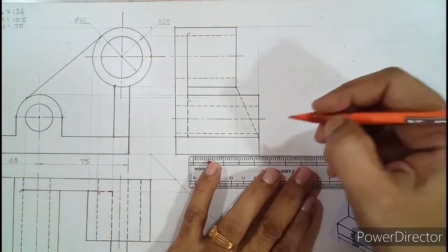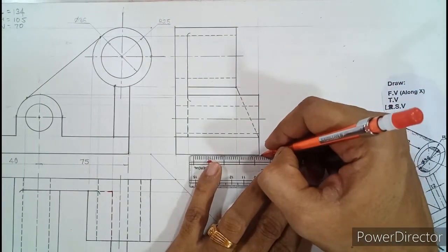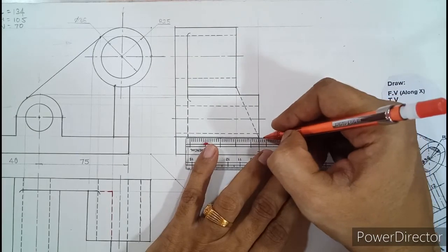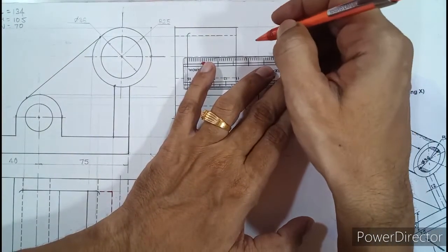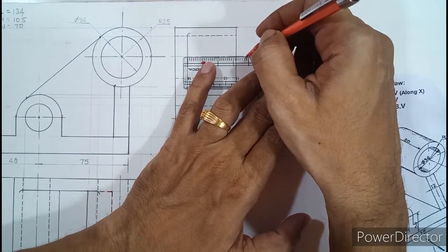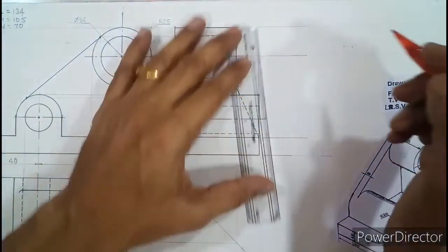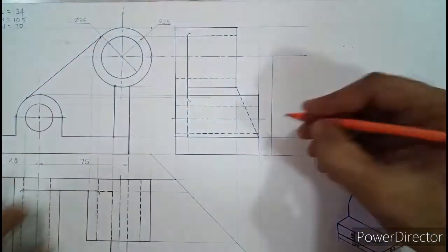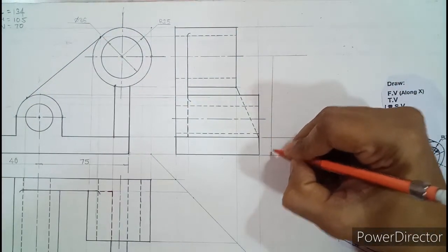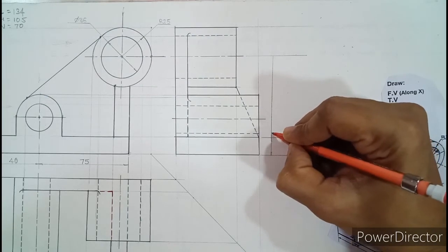So what we can do is, from here we can draw a medium dark extension line till this base plate 15 mm, and then till the center of the above circle you can draw one more extension line. From here leave 8 to 10 mm gap, and here you show dimension 15 and 65.